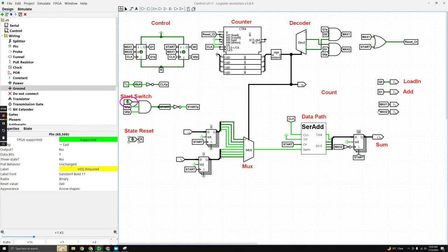Our sum is in hexadecimal, so this does not actually read 13. Since our circuit and this output are in hexadecimal, this 1 actually carries a weight of 16. So it's 16 plus that 3 is 19, which gives you the C plus 7. Just to clear some things up.